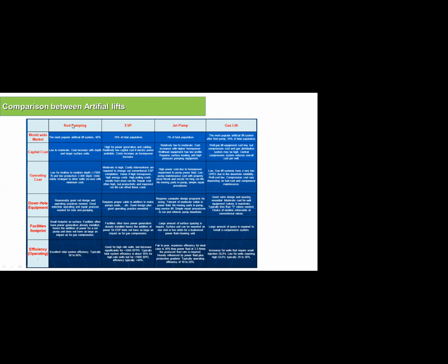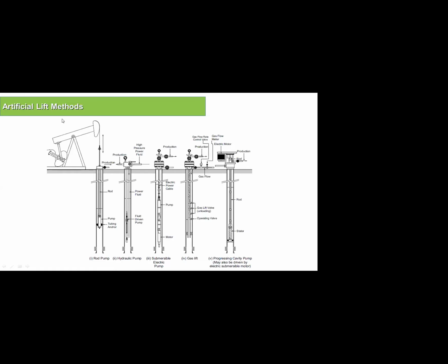If we look again at this curve, you will find that the sucker rod has a big surface load print. It needs a big space. So I will speak about my company, GAPCO. GAPCO is one of the biggest offshore companies in Egypt, so most of our production is coming from offshore wells. It means we have a platform in the sea, and there isn't a lot of space on the platform. So for us, introducing something like this is not possible. The sucker rod pump as an artificial lift method is not an option for me.